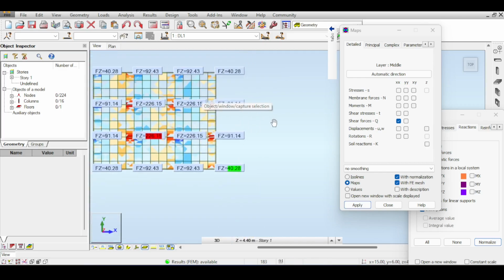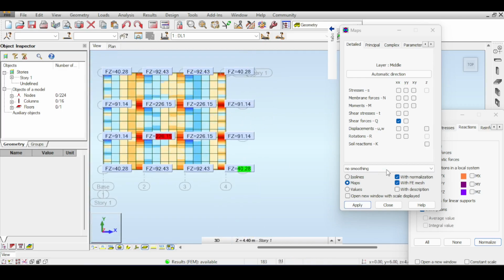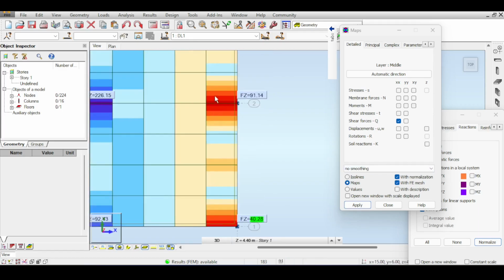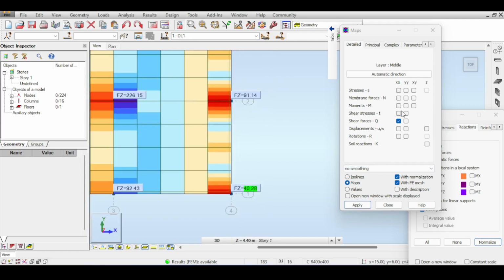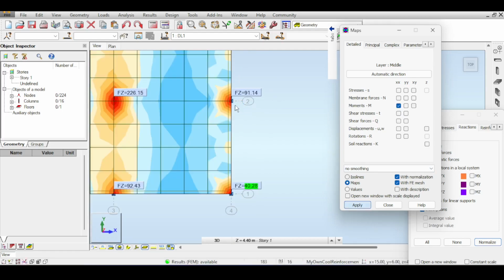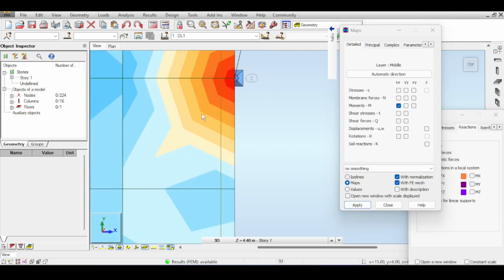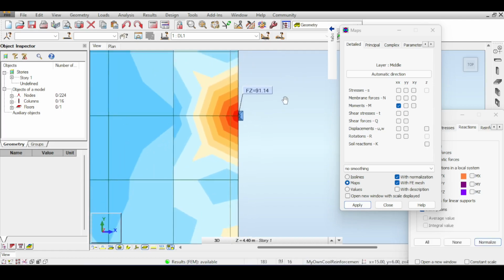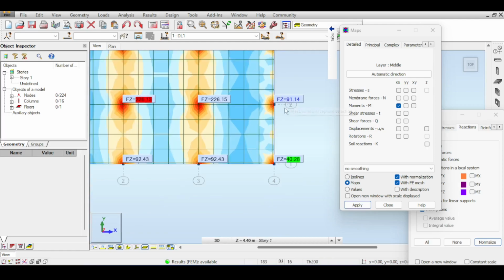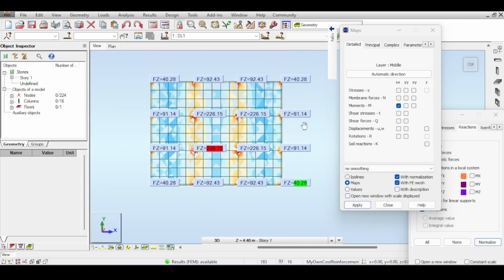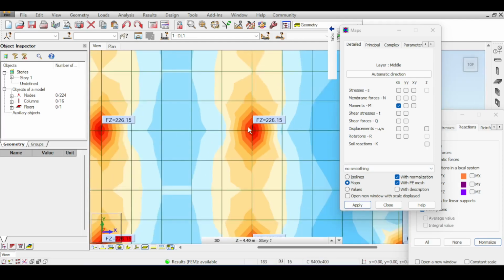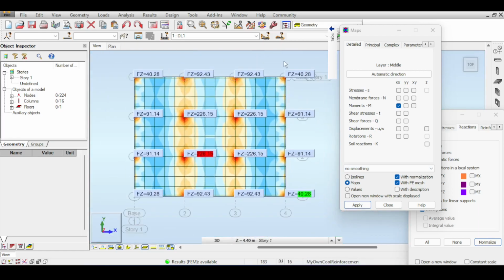This scales quickly. Now, of course, I removed smoothing because I want to get the raw values of the finite element. For the moment, you will see a somewhat bilinear equation. You can see basically a diagonal here. You have a linear increase here and a linear increase here. Some of you like to call this a parabola, but I disagree. So, of course, we are talking no smoothing now. And notice, without smoothing, the finite element mesh still looks cool.